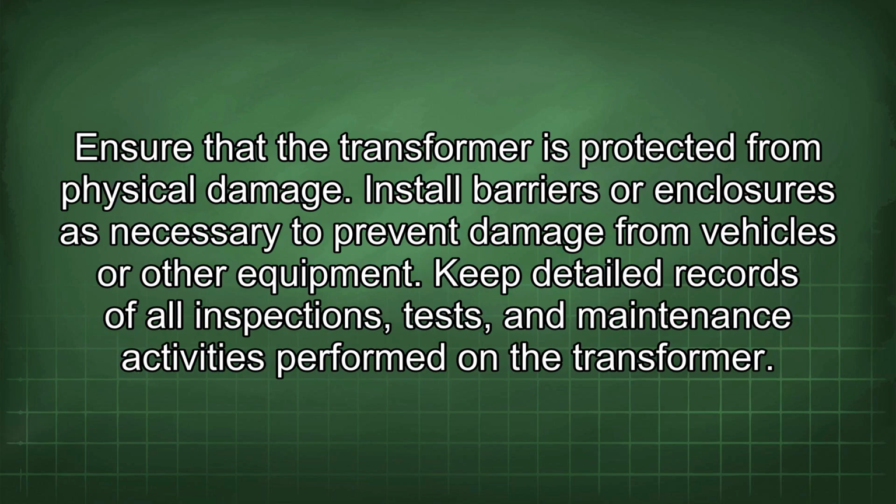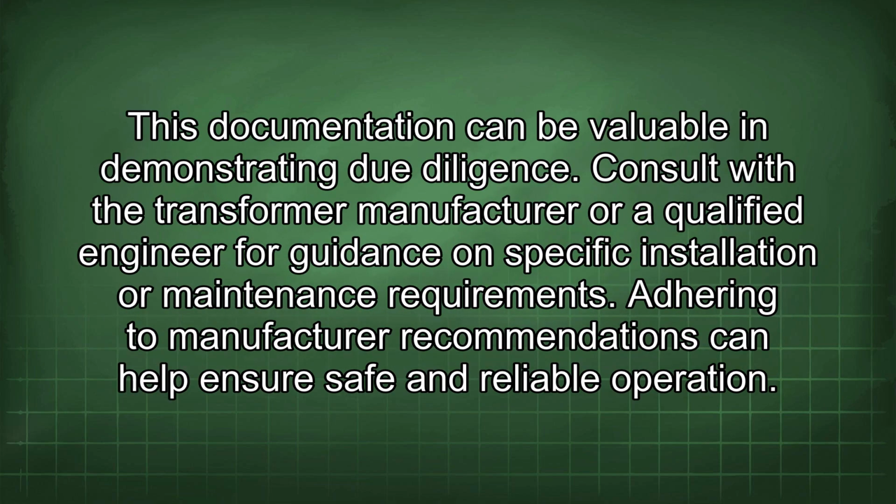Ensure that the transformer is protected from physical damage. Install barriers or enclosures as necessary to prevent damage from vehicles or other equipment. Keep detailed records of all inspections, tests, and maintenance activities performed on the transformer. This documentation can be valuable in demonstrating due diligence.